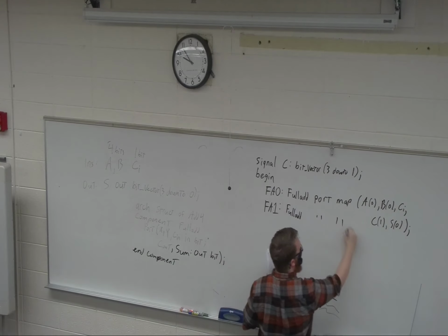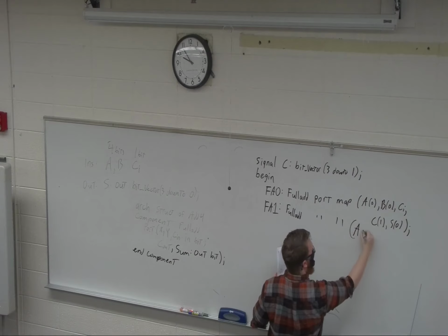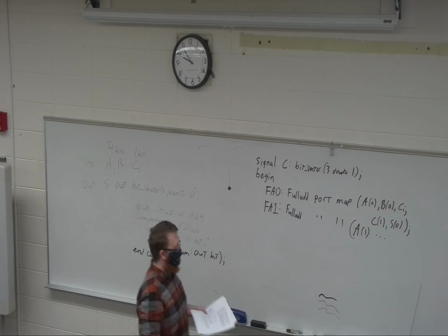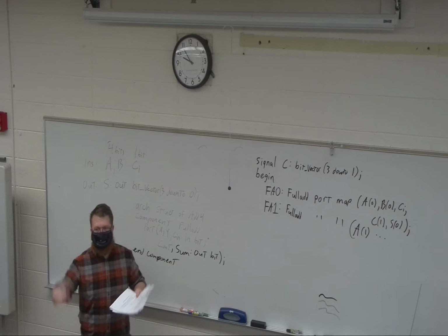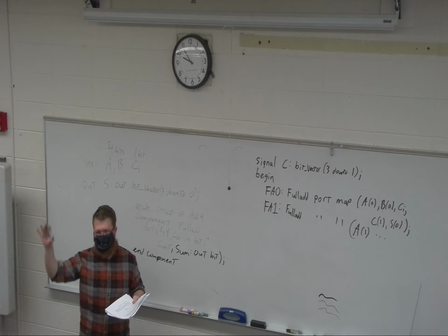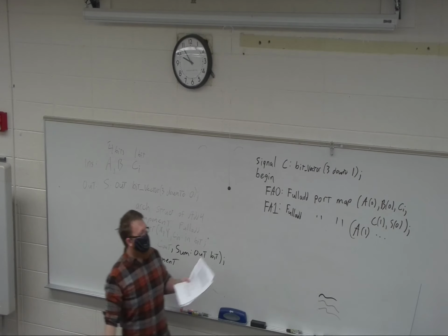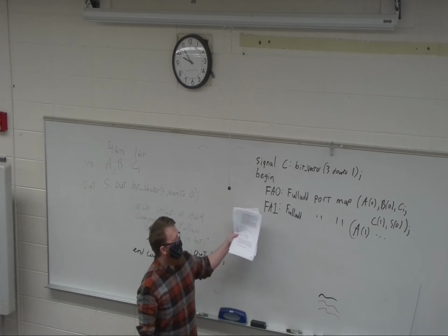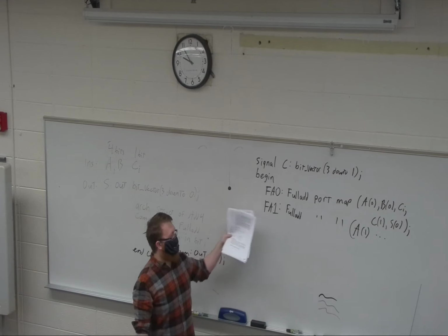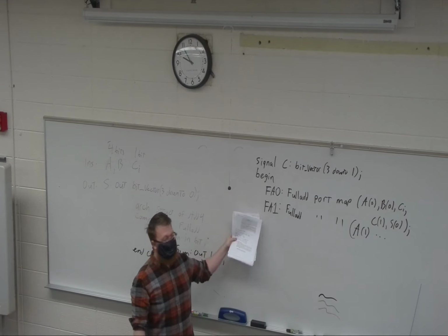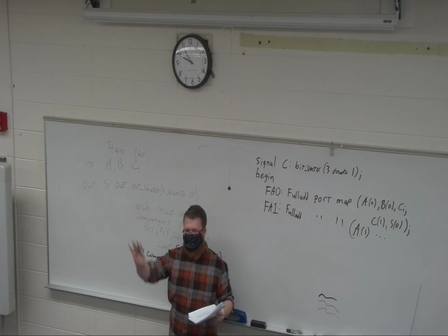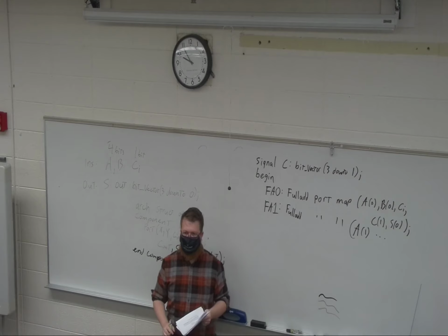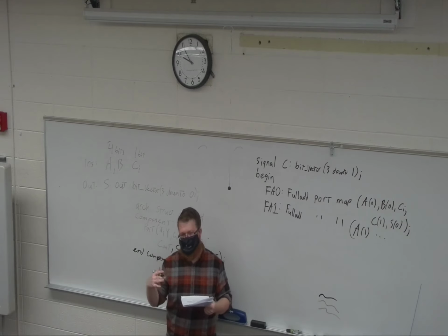Port map, and so on and so forth. So I have this 4-bit A, a 4-bit B, a 4-bit C, and now I'm telling them that the first full adder wants the 0th bit, the second adder wants the first bit, and so on. So I'm just mapping the upper level module down to each of these modules, or sub-modules.